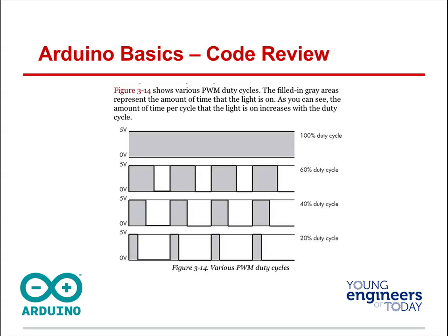So this, again, we're blowing this up so you can see it. When it's 5 volts, that's not the important part. The point is it's on full blast this whole time. At this point, there's a significant amount of time during the duty cycle where it's set back down to 0 volts. There's no value. So it's going high to 5 all the way across up here. Here it's high to 5, back down to 0, and then back. And it's just little spikes. Well, this is going to look dim to our eyes compared to that being very bright.